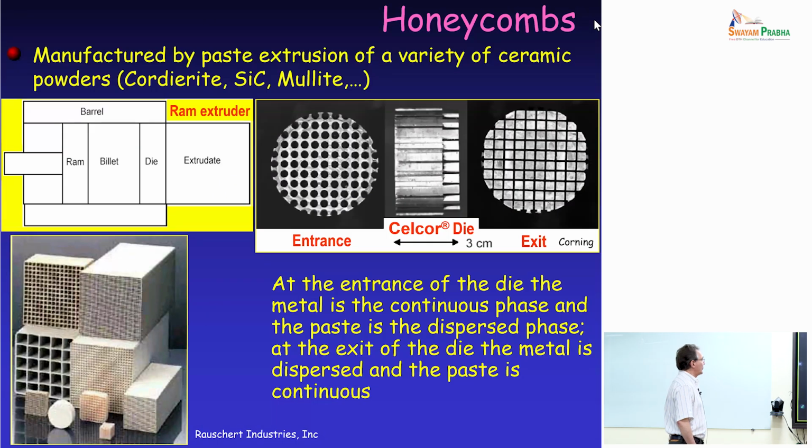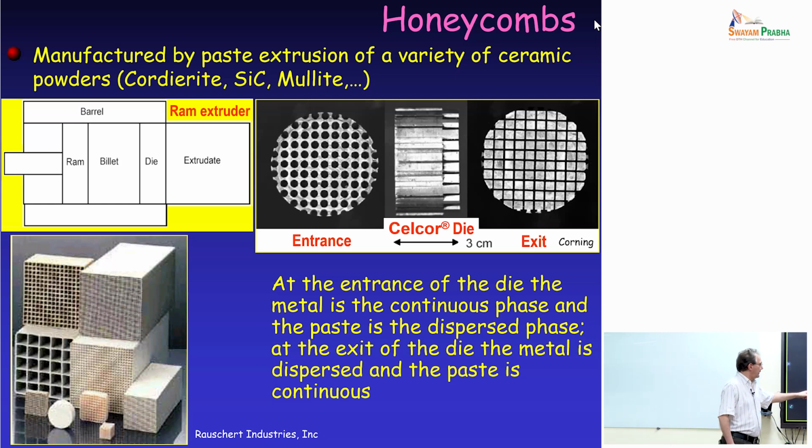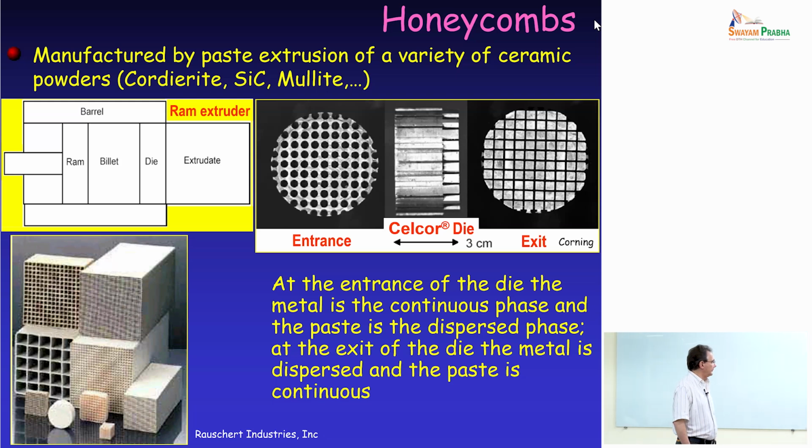Extrusion is, of course, one very good way of obtaining specific types of highly porous ceramics. The advantage of this approach is that you have a high permeability. You also have high strength parallel to the extrusion direction. The strength perpendicular to the extrusion direction is much lower.